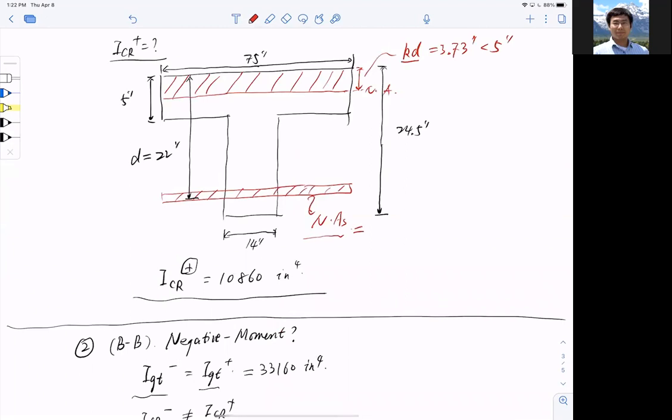In case you're wondering, Bob, you didn't do it here. This is relatively simple: 8 multiplied by As, 2 number 9 bars, so 2 inch squared, plus 2 number 8 bars, 1.58 inch squared. This number I calculated out to be 28.64 inch squared.